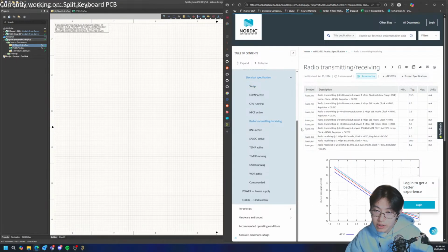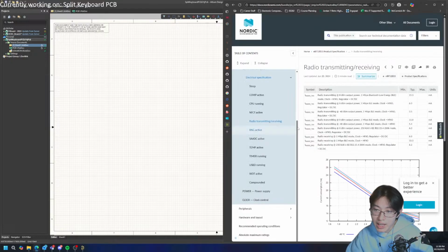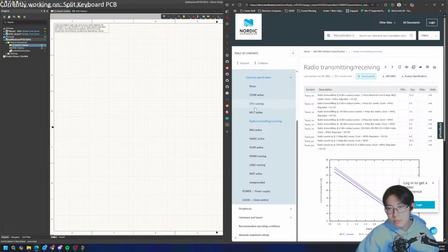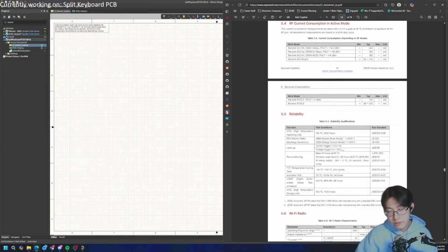Okay, so radio transmitting / receiving is what I'm looking at. See, even with this, Bluetooth low energy mode, 8 dBm output power, 15.5 milliamps versus 130. It's almost a factor of 10. Like, that's actually insane. What the heck? Oh. Maybe I'm gonna have to go with the Nordic chip then, if I want this to be any semblance of...